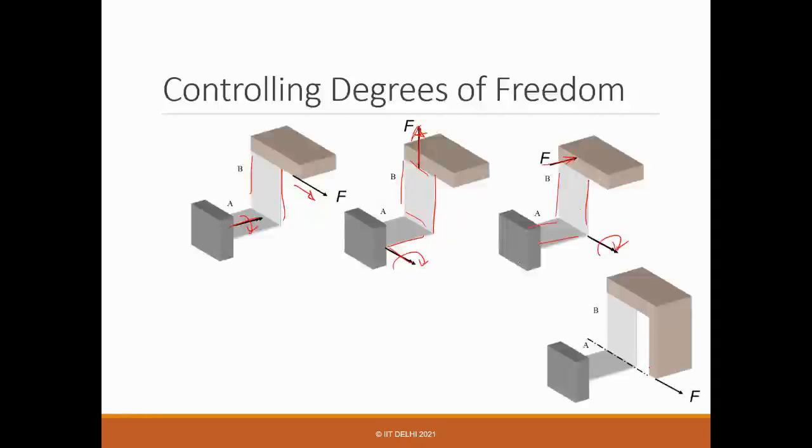But what happens if you apply a force along the fold line? In this case, it is very counterintuitive, but you can write bending equations using simple theory, and what you realize is that there will be no deformation. One way to look at it is it's lying on the plane.